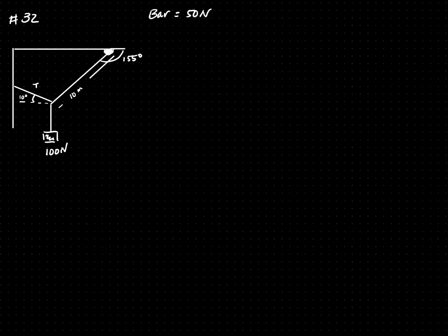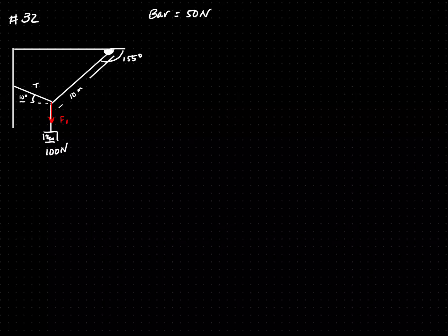You want to start by drawing the forces in the picture because this is at static equilibrium. There are 5 forces. There's a force from the hanging weight, which I will label F1. You have a weight force from the bar because a weight was given, which is Fg, and it's going to be midway. We are going to have a tension along the rope, and then you will have a force at the hinge right up here.